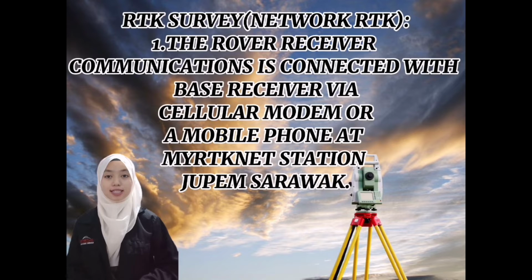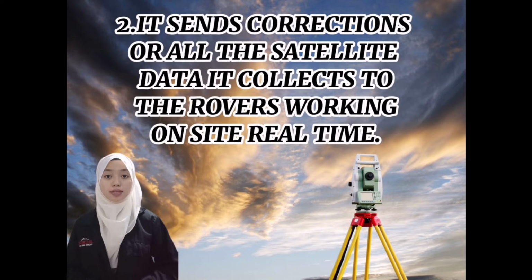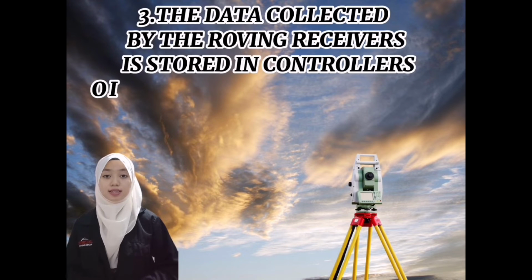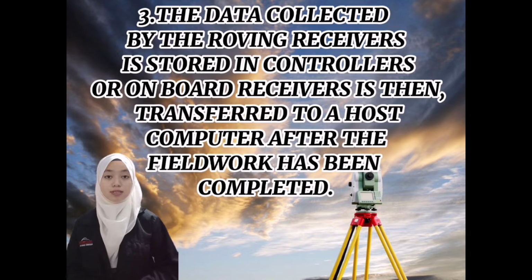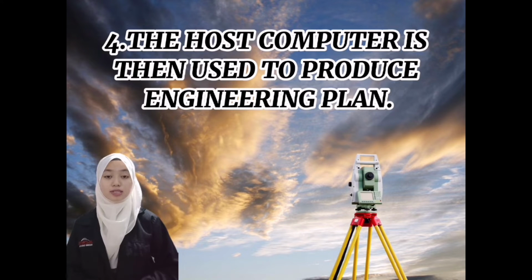RTK Survey, Network RTK. First, the rover receiver communication is connected with the base receiver via cellular modem or a mobile phone at MyRTKnet Station, Kuching, Sarawak. Second, it sends correction or all the satellite data it collects to the rovers working on site in real time. Third, the data collected by the roving receiver is stored in controllers or onboard receivers, then transferred to a host computer after the fieldwork has been completed.